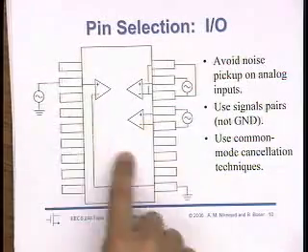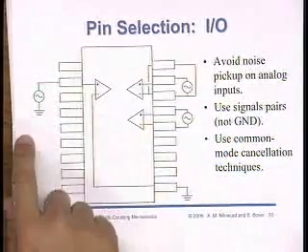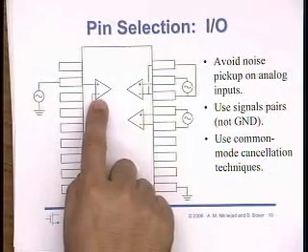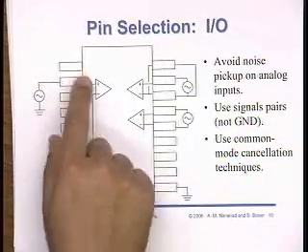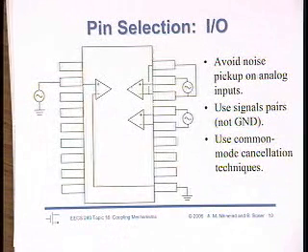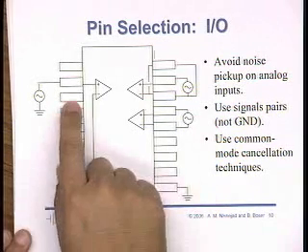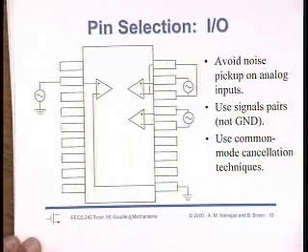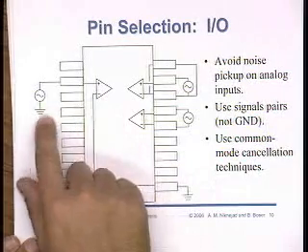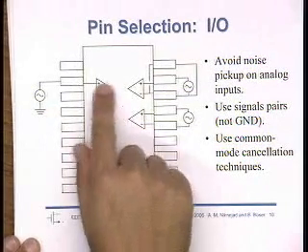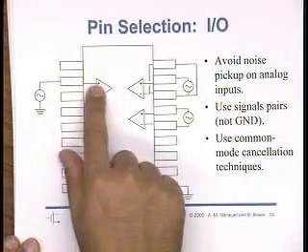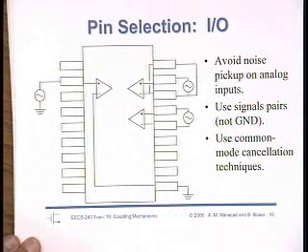So this loop here, if there's considerable power going through it, probably wouldn't be on an input, it would be on the output. But equally well, this could be an output stage, and then that's a source of interference. If it's a big loop on the input, it's a good sink for interference, if you will. It's a good way to pick up interference. And it's a problem because this interference signal could compete with your tiny signal here. Or even worse, it could totally swamp out your tiny signal and saturate this amplifier. Remember, this amplifier potentially has a lot of gain. So that tiny little interference signal can totally saturate your amplifier stage, and now your circuit just doesn't work.